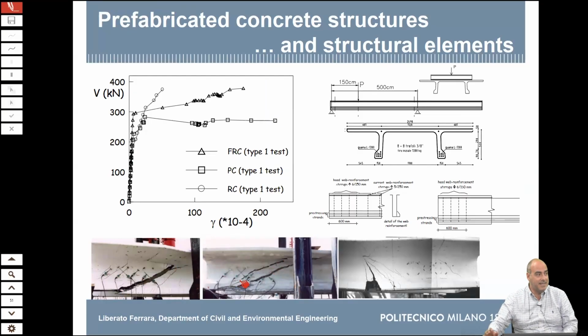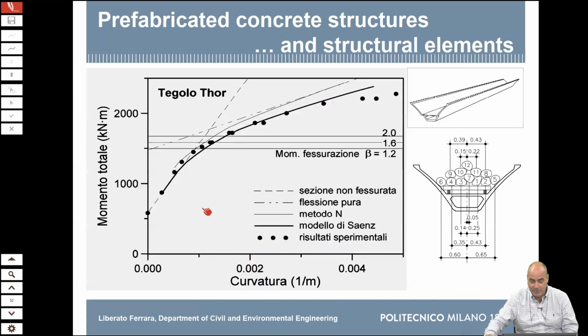And you can clearly see the strut and tie mechanism which is formed, because these two cracks clearly highlight the strut in the mechanism. This one here was with fibers. The interesting part was that there were 80 kilos per cubic meter of fiber, so it was a good fiber reinforced concrete. And the mechanism of failure shifted from shear towards shear flexure. You can see here that there are several cracks, but also some failure at the compression part, because it's going into the flexural mechanism.